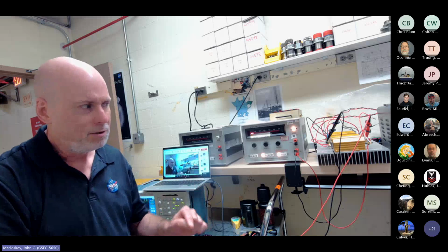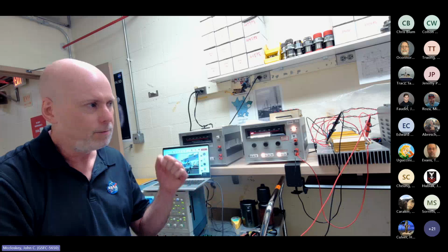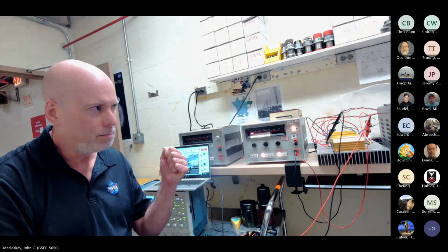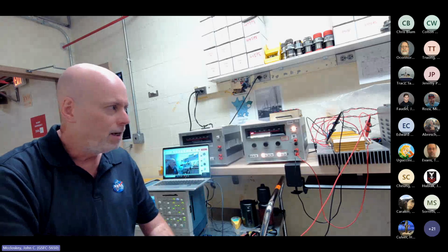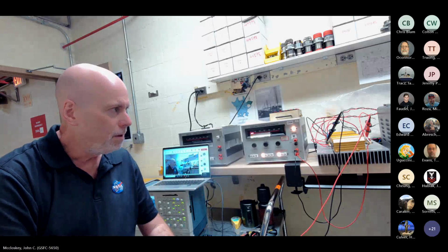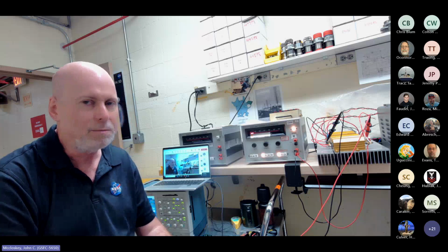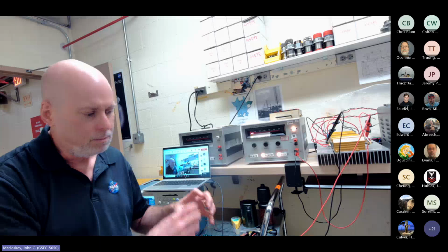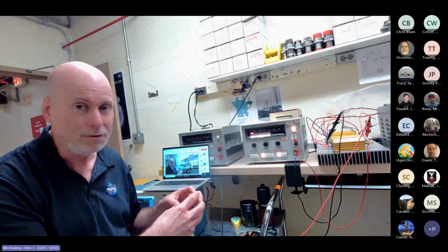And for the turn on transient, the worst case was, pretty sure, one of the cryocooler boxes. Cryocoolers are very current intensive devices. And I believe the turn on transient magnitude was over 30 amps for about 25 milliseconds. So this wasn't a transient so much as a level shift.